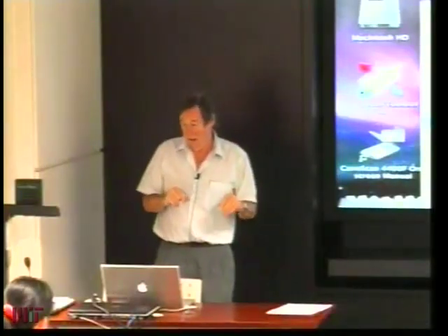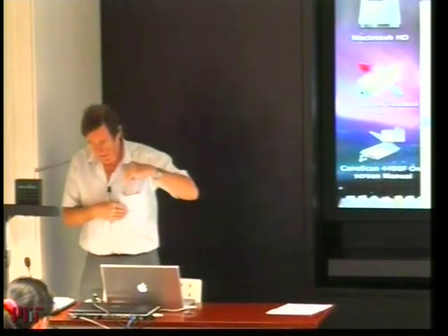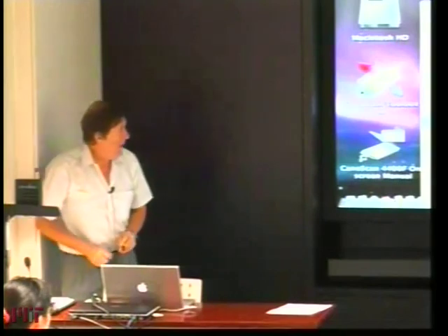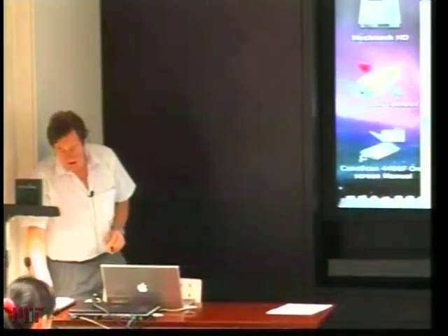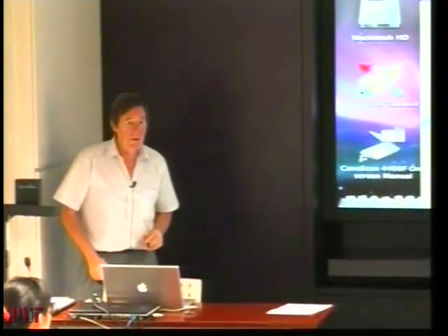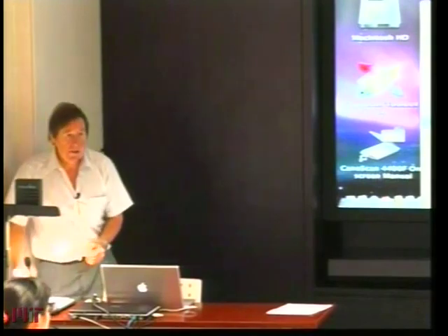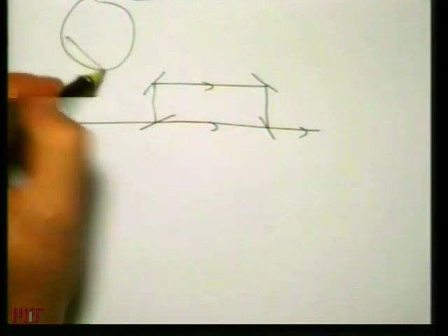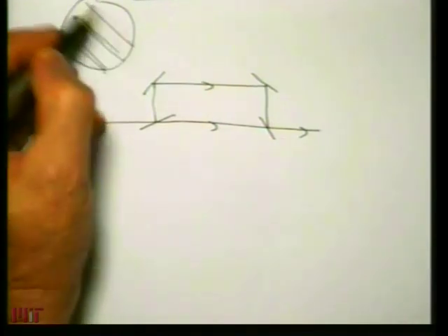I see. But if you tilted the system, then you would get some fringes. Yes. And the sort of thing you might see is, let's say you put in a disk of material like this, and you're trying to measure the thickness of this disk. If it was nicely uniformly thick, you'd find that you got these regular fringes across here.